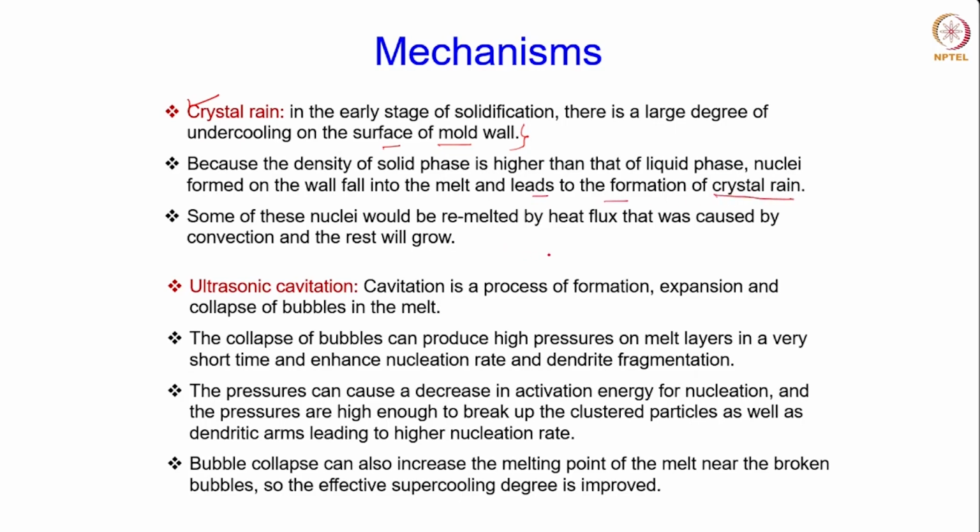Okay, so if you have looked at the microstructure in a mold, as to how the grains solidify, you would see that near the mold you have a high undercooling because the mold leads to a chilling effect, right? Here the heat transfer rate is much higher, the cooling rate is higher, okay?